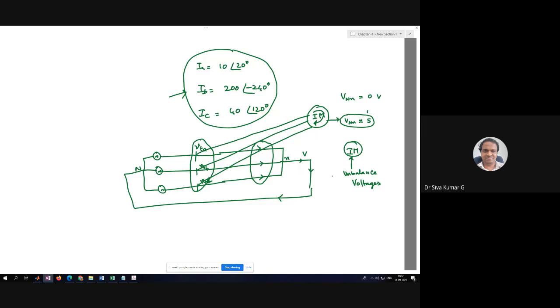What is the main thing is, as the power quality definition says, the system should have a satisfactory performance. But when you have the voltage unbalance, for an induction motor application we experience a pulsating torque, which is not allowed in a system.